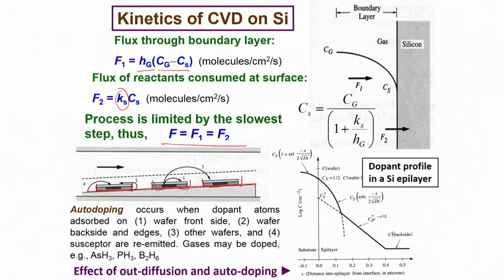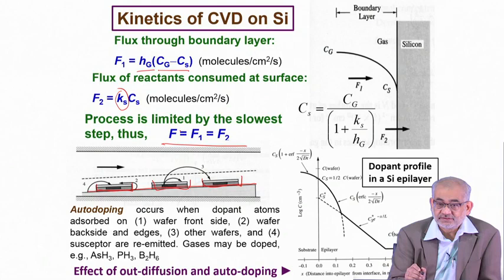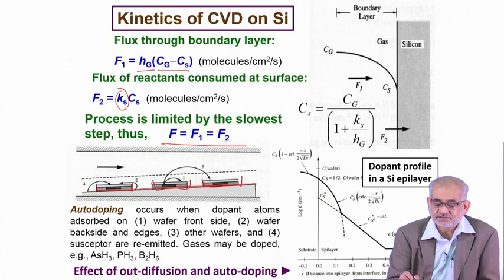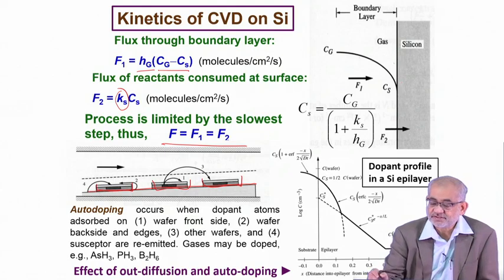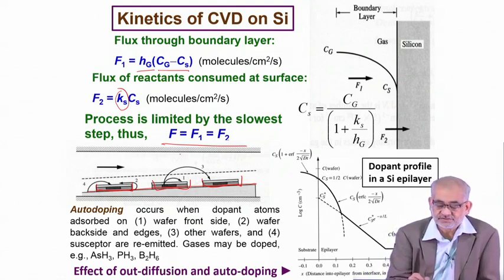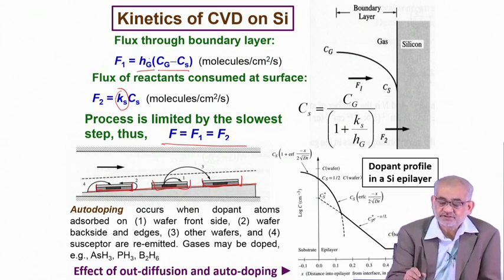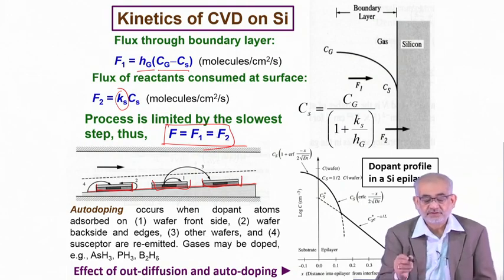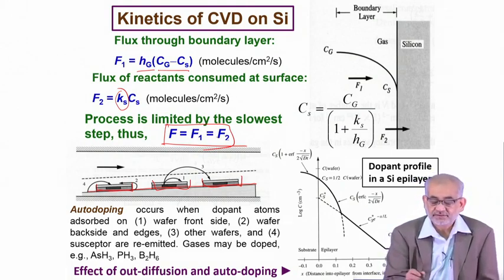So the overall flux, when the situation is controlled very optimally, will be equal both away from the substrate surface and very close to the surface, because one of the steps, which could be due to partition coefficient or the convection or the concentration, will actually make this condition valid, that the flux will be equal both away from the boundary layer, at the top of the boundary layer, or at the surface.